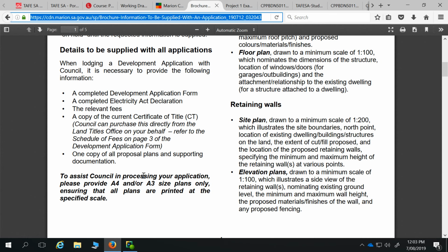So that means that the main development plan overrides. So I could go to the sides, 8 metres on one boundary. But I didn't want to build on any boundary. I want 1 metre setback on the garage side and 2 metres on the other side. So they were quite happy with that, because they said, well, it's usually 3 metres on one side if the boundary's on. If you're building on the boundary, you've got 3 metres between both sides, which is sort of the same. And we'd prefer that, because now you're leaving a bit more space between the houses.